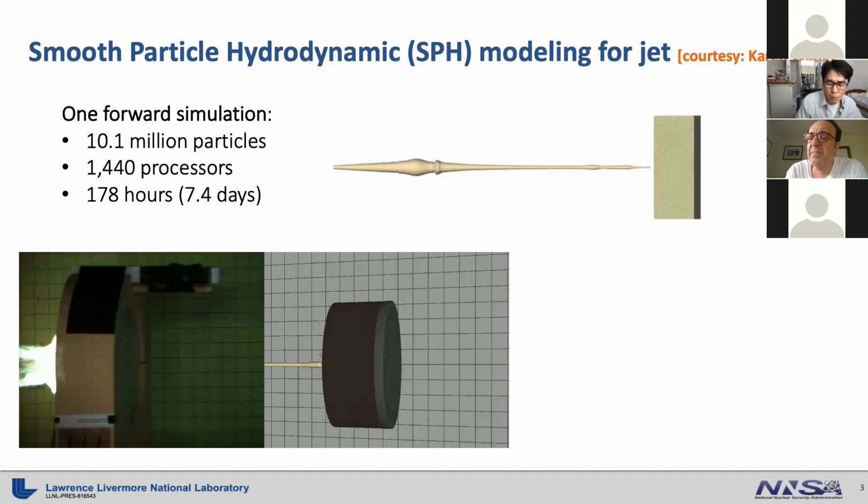And then the goal of the reduced model, I don't know, philosophically, is that there is an underlying, corresponding full order model, discretized, highly resolved solutions out there. That's why we use those data. And then with the reduced model, we try to predict and achieve the same level of fidelity for the new points using those subspaces we learned through the reduced model construction process. So I would phrase it that way, the concept of learning in reduced models.